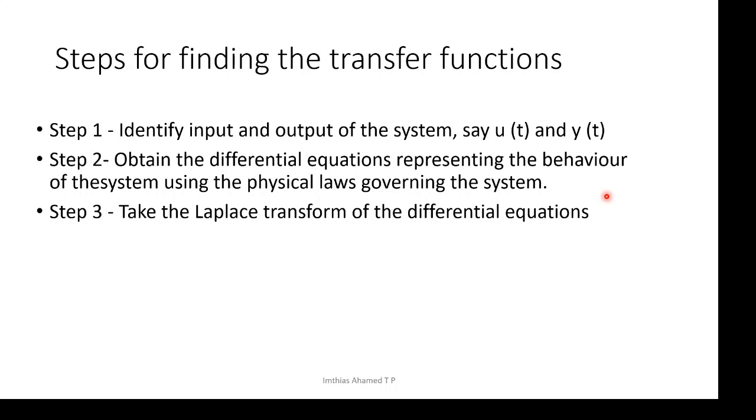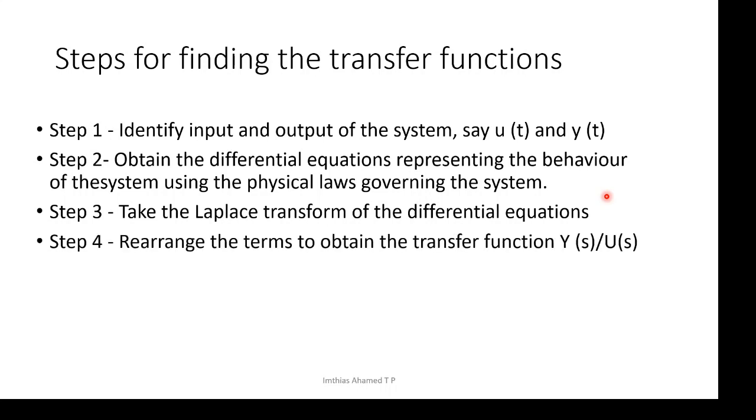That is, if Laplace transform of y(t) is Y(s), Laplace transform of d/dt of y(t) will be equal to, I will pause for a while, you think? Yes, you got the answer, it is sY(s). So, you have to find the Laplace transform of the differential equations, and step 4 is rearrange the terms to obtain Y(s) by U(s). You have learned that transfer function is Laplace transform of the output y(t) by Laplace transform of the input u(t). This is our objective.